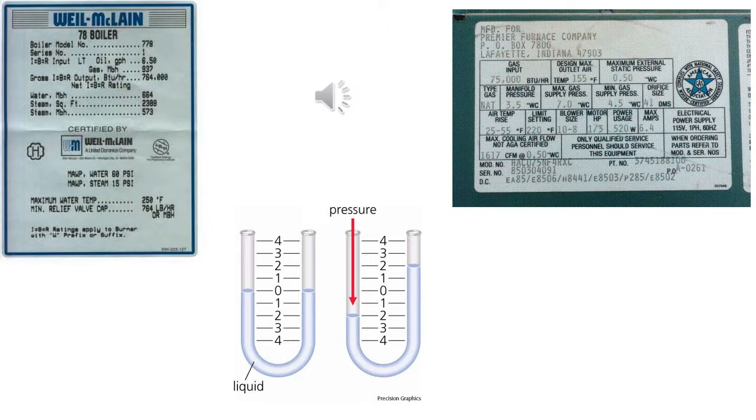When making low pressure readings that are a fraction of a pound, inches of water column is used. The unit of measurement refers to how many inches of water will create the pressure. Instead of using PSI as the unit of measurement, we use inches of water column to measure gas pressure because the pressure measurements are so small. 1 inch of water column is equal to 0.036 PSI, or another way to look at it, is that 1 PSI is equal to 27.7 inches of water column, which we round to 28 inches of water column.